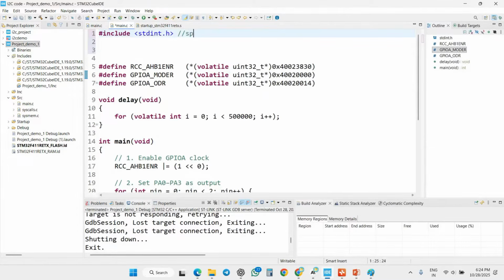We can use specific bits, or we can configure unsigned integers if you want to. You just use this header file. That's the purpose. If you don't need specific sizes, you can simply use stdio.h. If you're only using int, char kind of things, you just use stdio.h. But I want to use specific bits, so I'm using this concept.